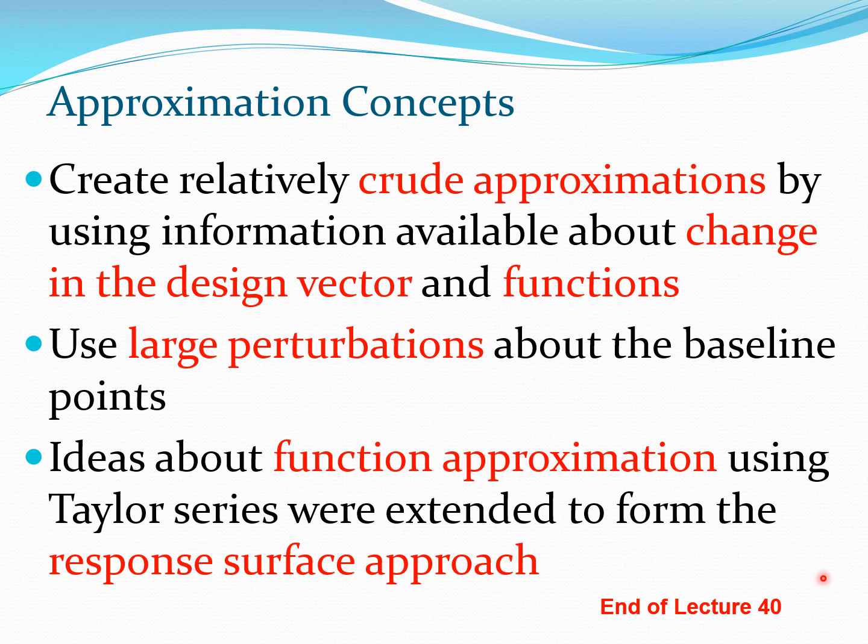So this concept was actually played around a lot with Taylor series, and then finally it gelled into the response surface method, where some people realized that you can use a different approach. Instead of using the Taylor series to create these functions, you could use theories based on the design of experiments, which is a field which is somewhat disparate from our current field. But in fact, that's where they decide where to run their experiments at a set of points so that they can form a good model of the system.